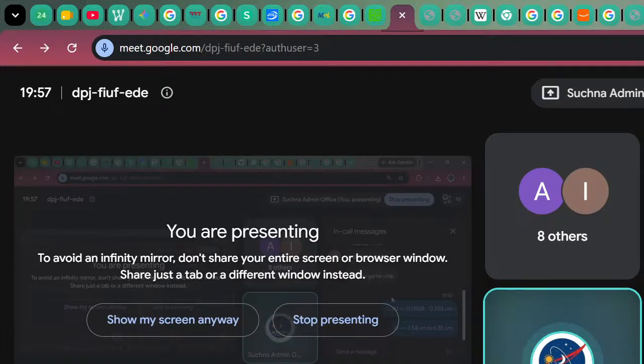This is according to the IPC 4552 specification. The thickness of the nickel should be 2.54 micrometer to 6.35 micrometer. So now the question is, can I put greater than 6.35 micrometer? Is it possible? Can we put the thickness of the nickel greater than 6.35 micrometer?